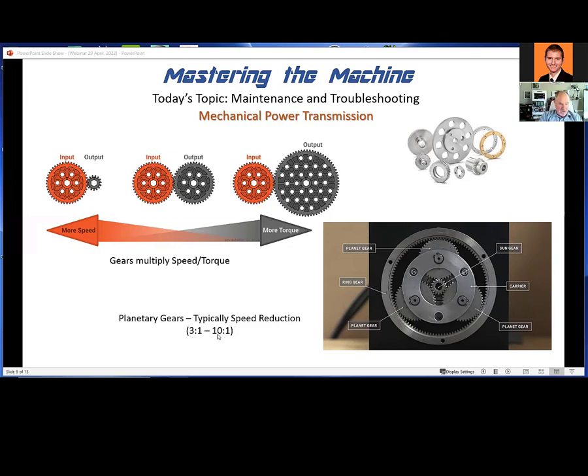If you get very much higher, then... and this one here actually looks like it's a higher speed, but I would say the ratio is this inner gear to one of these gears, and that's basically your gear ratio. But this is very stable, inline, and doesn't have a lot of backlash, which is one of the reasons they use these planetary gearboxes. Another reason is that it's pretty compact, right? You're not putting gears just side by side. You're putting them basically in line with each other.